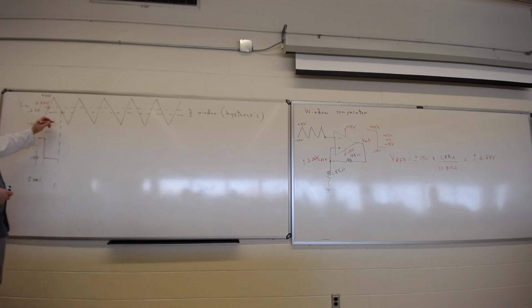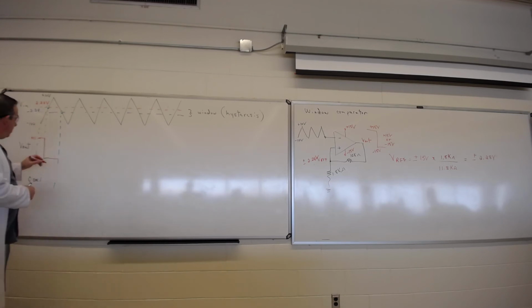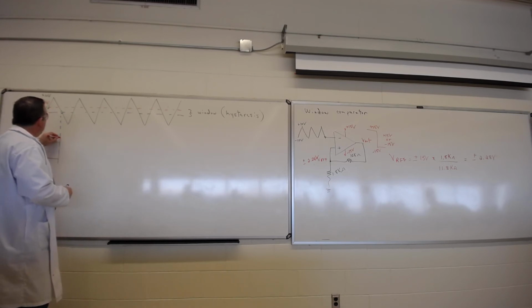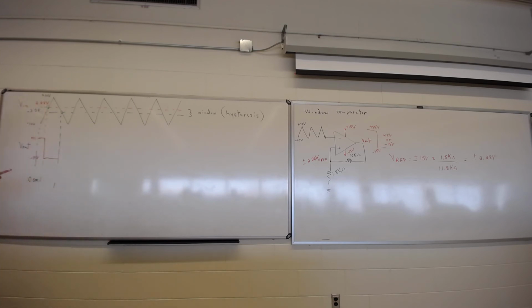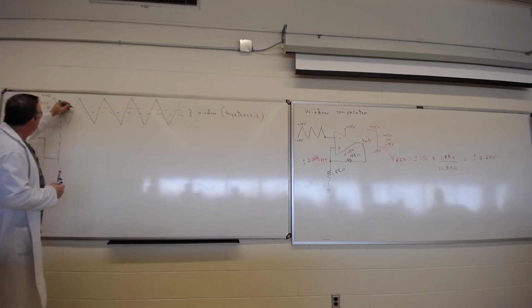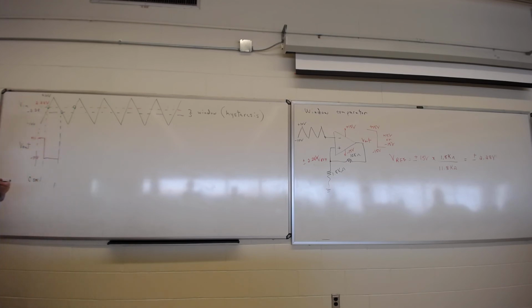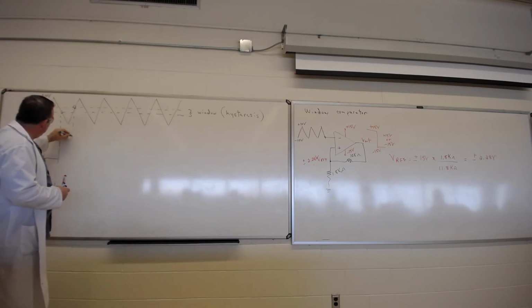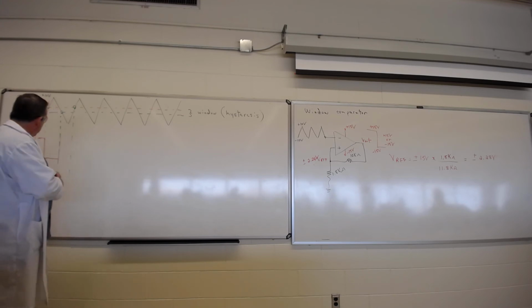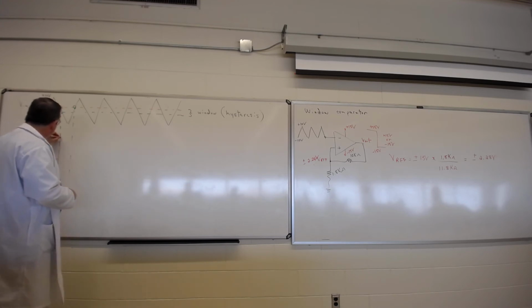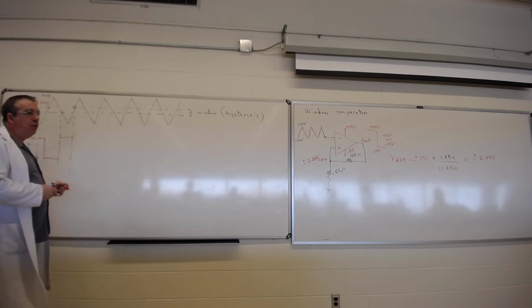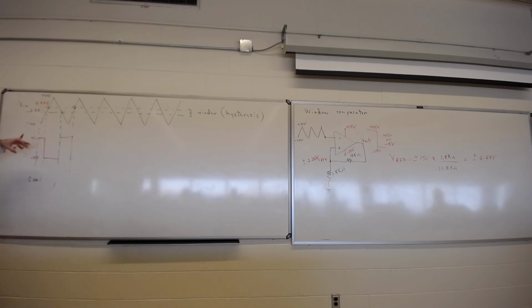And when the signal drops below the negative 2.28, up it goes. And guess what? There's the reference point, the switching point. It flies over here. So nothing changes until it hits this point over here, and when it hits that point, bang, it switches back. See what's going on here? Every time the output switches, the reference point, the threshold, switches over.